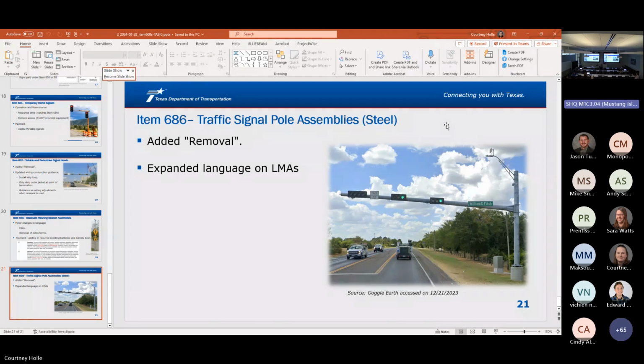The first time when we went through with it, it seemed like the consensus was to do the round column attachment. But as we developed it and got comments back, it seemed like the other one was also of interest. So we went ahead and designed both of them. But the thought is going from the loading of the truss and really just focusing on that connection. And then we've specified limitations of what our assumptions were for the concrete column part, because the height of the column does affect the loading. And so we put those assumptions in there.